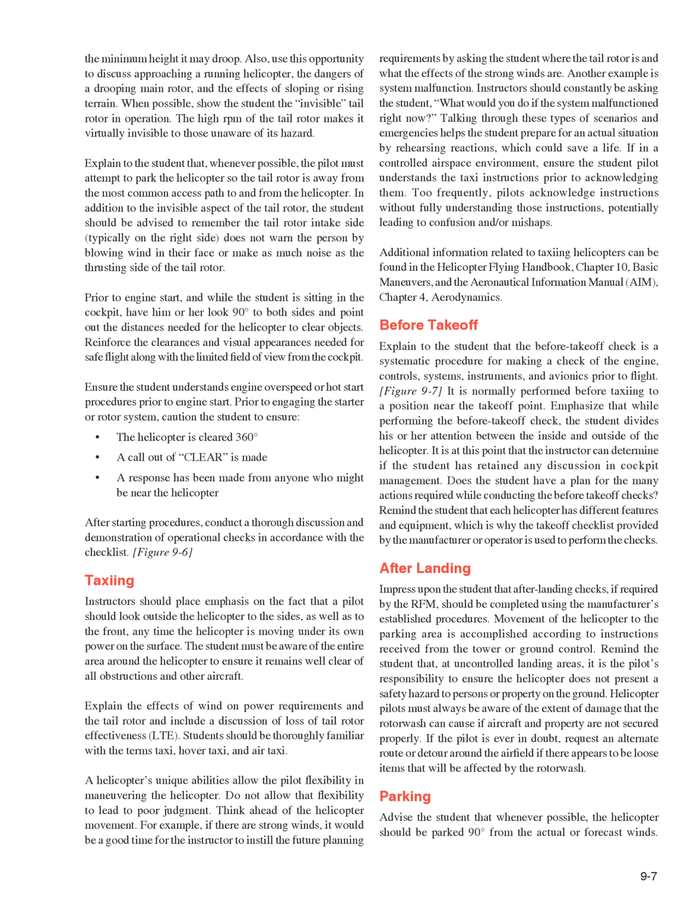Ensure the student understands engine overspeed or hot start procedures prior to engine start. Prior to engaging the starter or rotor system, caution the student to ensure the helicopter is cleared 360 degrees, a call out of clear is made, and a response has been made from anyone who might be near the helicopter after starting procedures. Conduct a thorough discussion and demonstration of operational checks in accordance with the checklist.